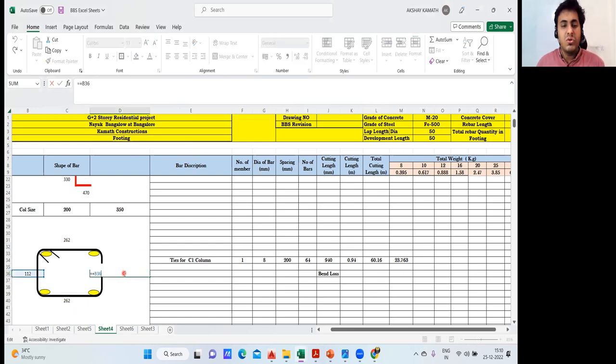This side also you know how you did this. I'll do it here. For this side, what I did, plus what was the breadth of that? So the breadth was 200 minus 40 mm from the left side, 40 mm from the right side, top 40 minus 40, and then minus the diameter of the stirrup. I'll get 112. Manually also I got the same thing. Agree with me?